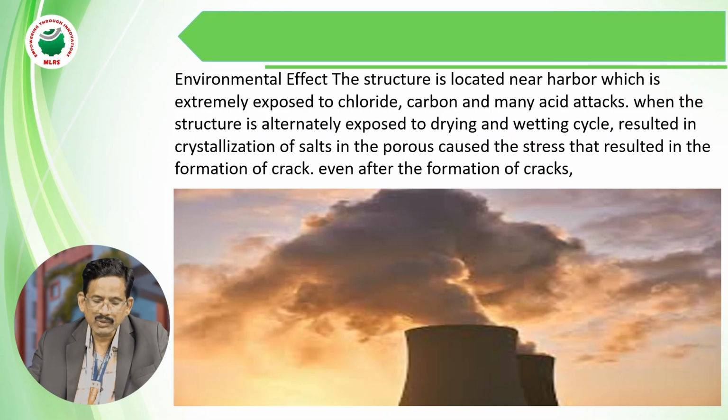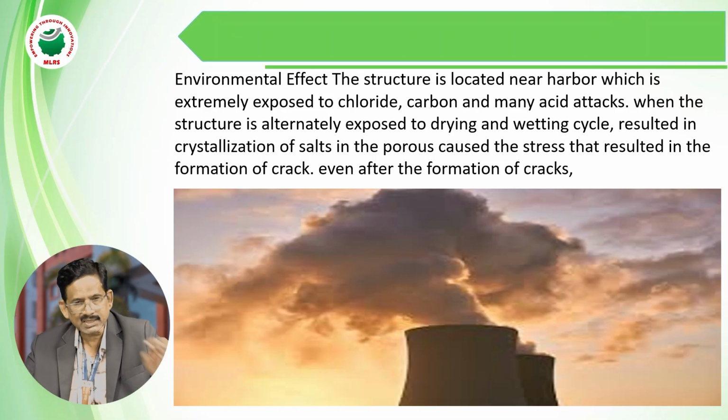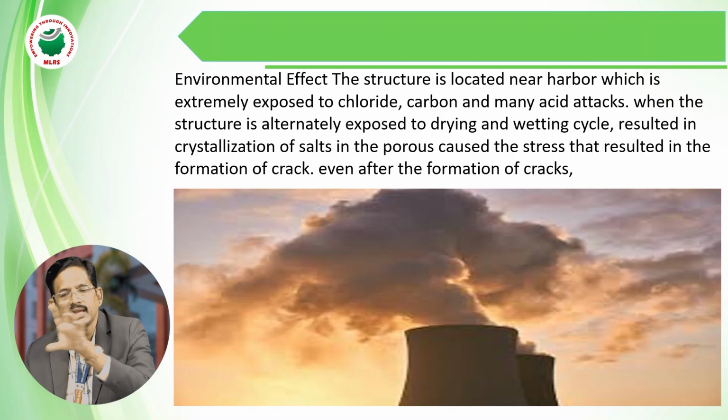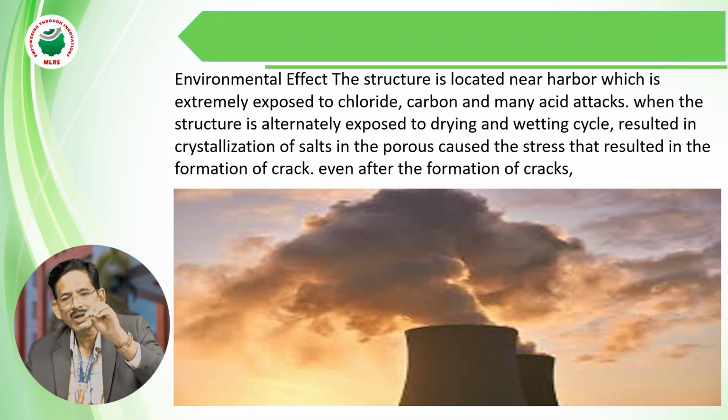Next, I will go to the environmental effect. What is the environmental effect? The structure is located near the harbour end. So, the Mangalore warehouse is located near the harbour, which is extremely exposed to the chloride contents. I told already in yesterday's class also, the rapid chloride permeability test is to be done in the laboratory, to check whether the concrete is subjected to chloride contents.